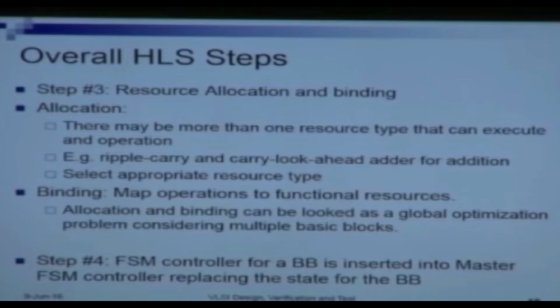So this allocation and binding step may be considered a global problem which considers multiple basic blocks at the same time. Finally, the last step of high level synthesis is to build the master controller, an FSM controller for a basic block. Because I have attached timing to each of the scheduling steps, I can generate a controller that appropriately activates the functional units and, through the appropriate select inputs, the correct registers and functional unit at a given time.